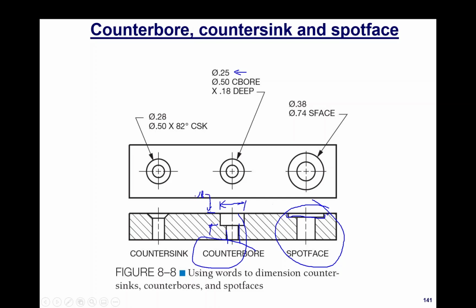With a spot face, we don't specify the depth. It is up to the machinist or whoever to give it a quick spot face. And you might say, well, why would I want that?